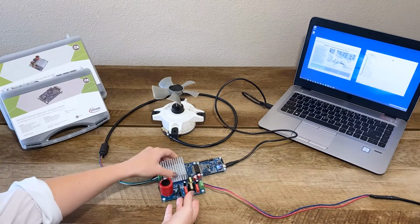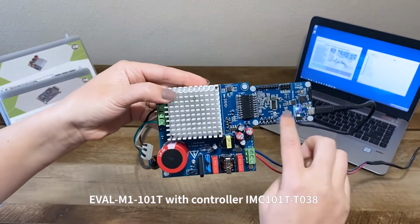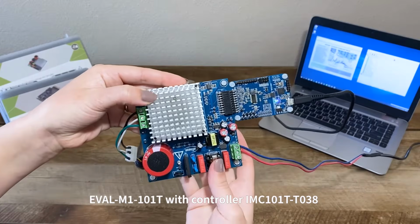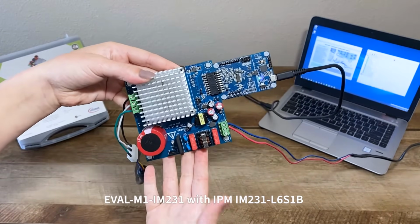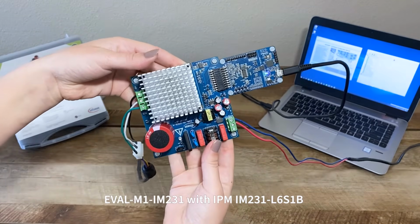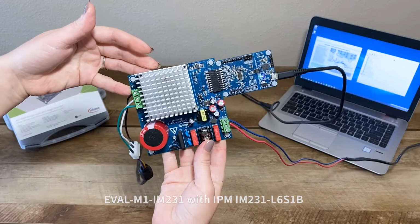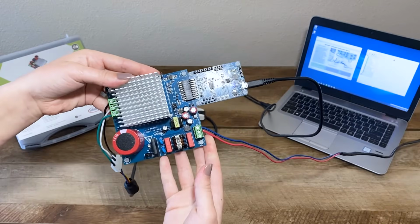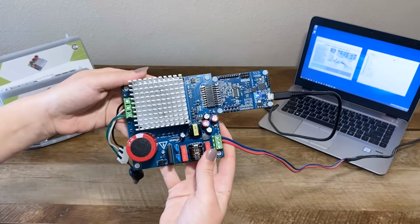your project. Here, I'm using the eval M1 101T control board designed with the IMC101T-T038 controller, and the power board I am using is the eval M IM231, which utilizes the IM231-L6S1B Intelligent Power Module, or IPM, which is hidden underneath this heatsink. If you're not familiar with IPMs, they are typically a three-phase inverter integrated with gate drivers and protection features to simplify your power stage design.